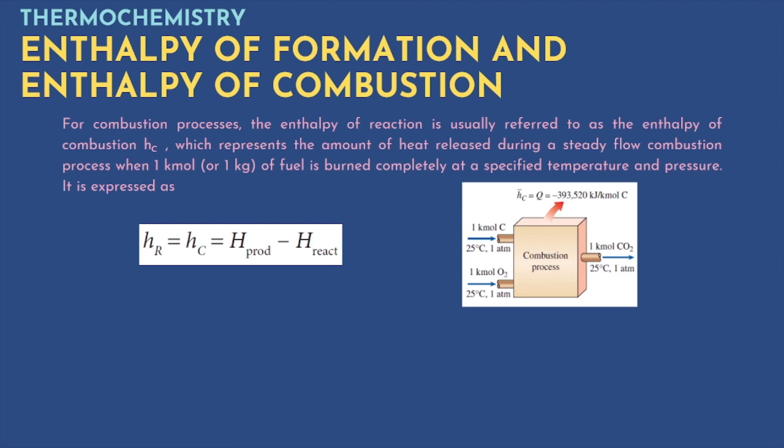For combustion processes, the enthalpy of reaction is usually referred to as the enthalpy of combustion, h lowercase c, which represents the amount of heat released during a steady flow combustion process. When 1 kilomole or 1 kg of fuel is burned completely at a specified temperature and pressure, it is expressed as HR is equal to HC is equal to H product minus H reactant.